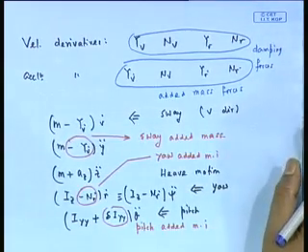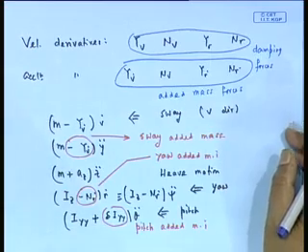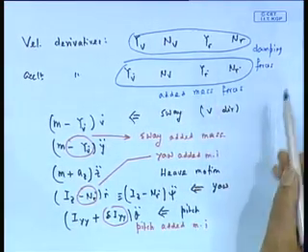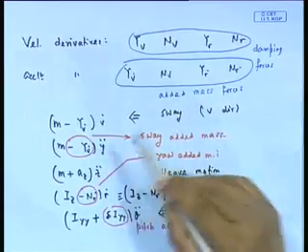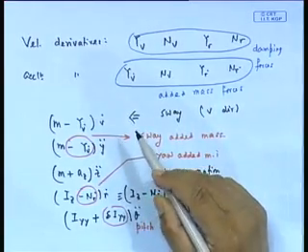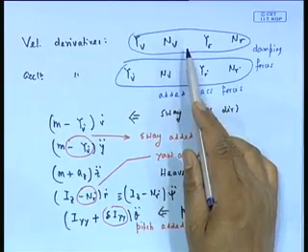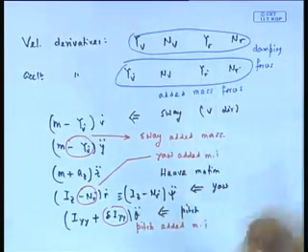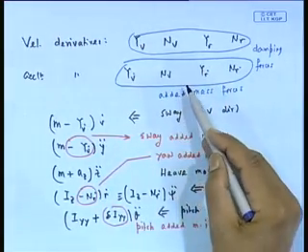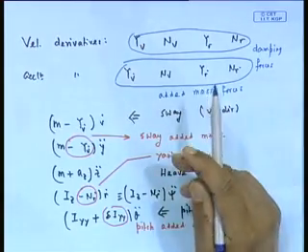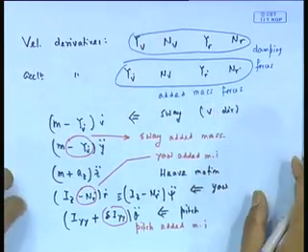I can call this damping forces, but I am hesitant to call that so straightforward, because you have to understand that in seakeeping I had added mass and damping. That damping arose because of free surface waves, because the ship created waves, but in this case they are not creating waves, and the phenomenon of this force is not same as that damping. In other words, there the damping was called radiation damping forces, that is what we call them in seakeeping. Let me write it down here, otherwise you will have confusion.